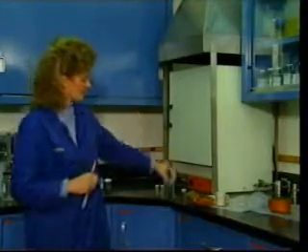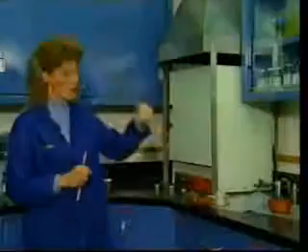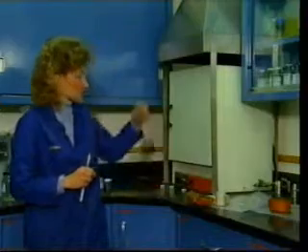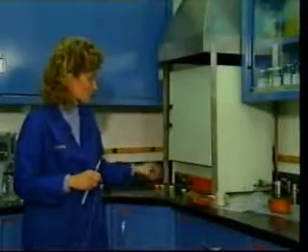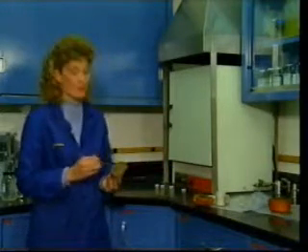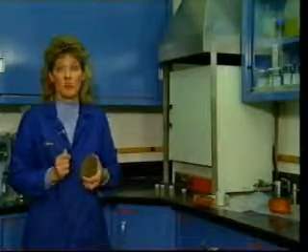This is 2% KCl. A similar thing happens in 3% ammonium chloride water, and also in a standard API brine. So what this has told us here is, although this sample appears to be consolidated, if they expect any water production whatsoever, the odds are good that they're going to have to gravel pack.